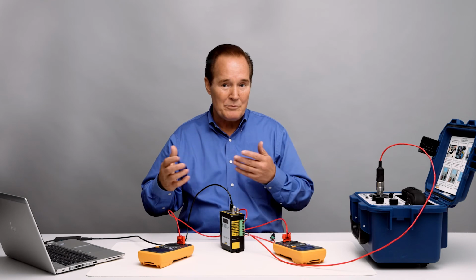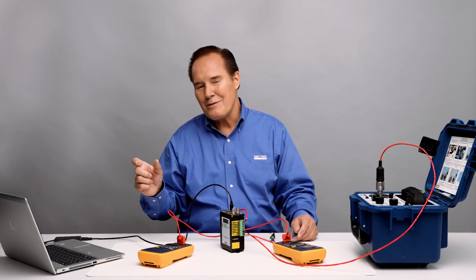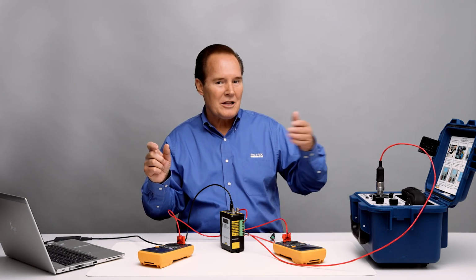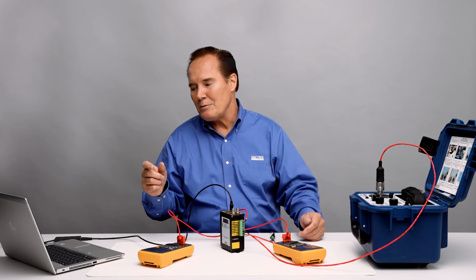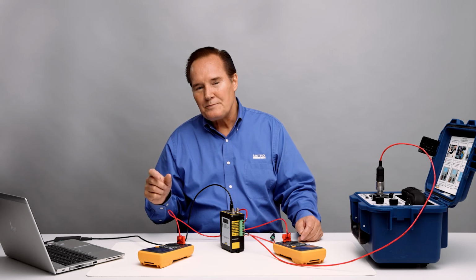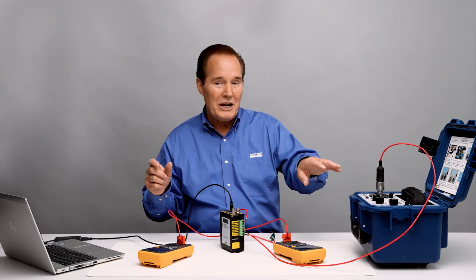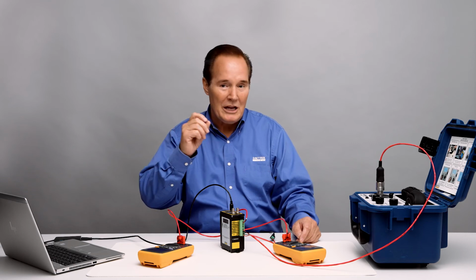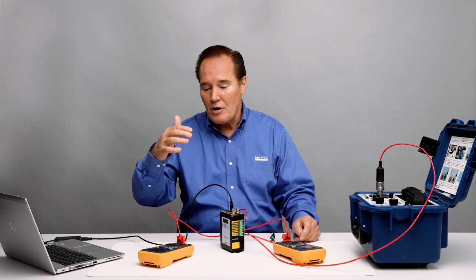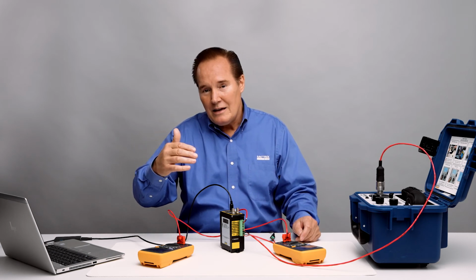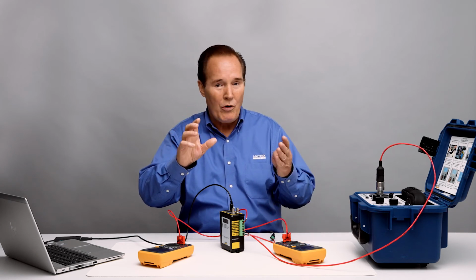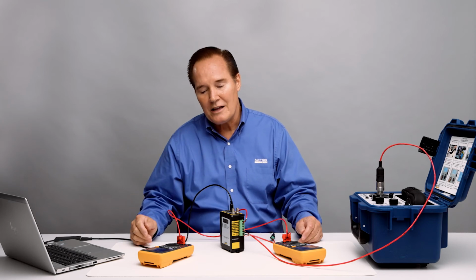That's what we're simulating, this impact event. Well, my window, because I simulated 2400 RPM, is only 0.4 seconds. So I had 16 throws of the piston. I calculated that to be 0.4 seconds at 2400 RPM. All right, 0.4 seconds times 20 hertz of the shaker means 8 hits. And remember, each impact event, as long as you're within the window, is 1 milliamp. Okay, so if you have 8 hits in that window, which we do, you go 8 hits, 8 milliamps plus 4 gives us 12 milliamps, and that's exactly what we see.